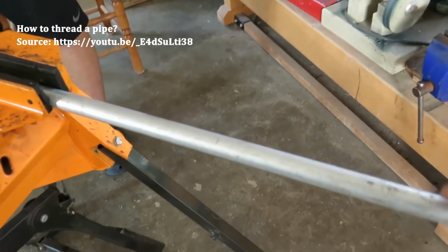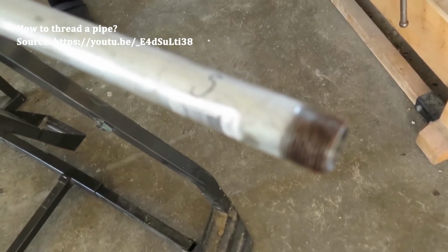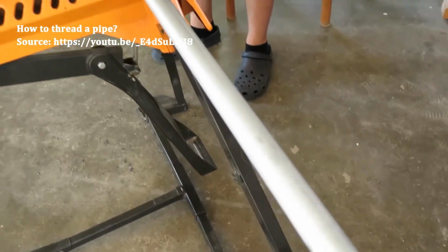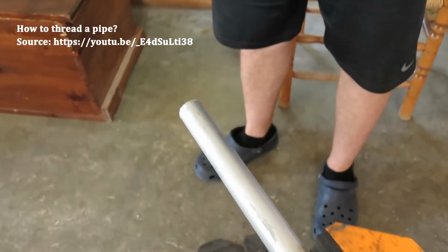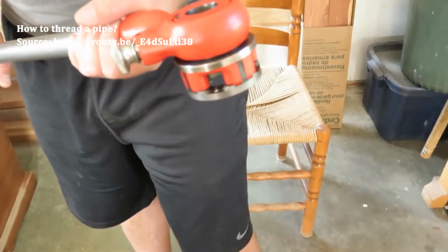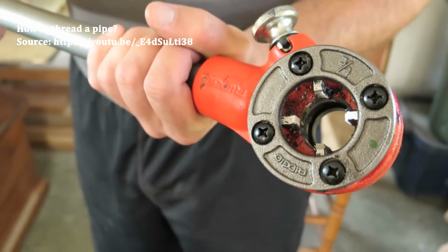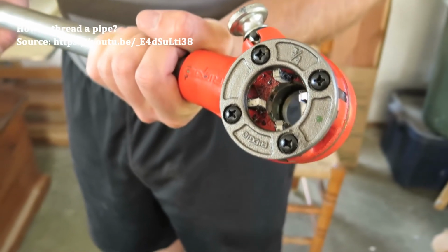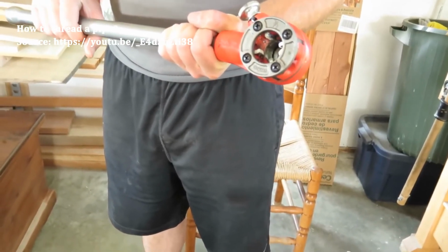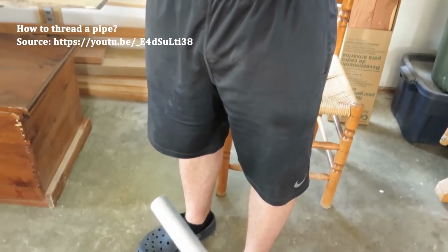We've cut this pipe to length, and when you buy a full length, you get threaded ends on both ends. But of course we've cut it, so now there's not a threaded end there, and we need a threaded end, and we're going to make that thread using this die. This is a hand tool that cuts threads in pipe. We have one size for 3/4 inch pipe and another die for 1 inch pipe, and that's what we're going to show you here. So we start by threading the die onto the end of the unthreaded pipe.